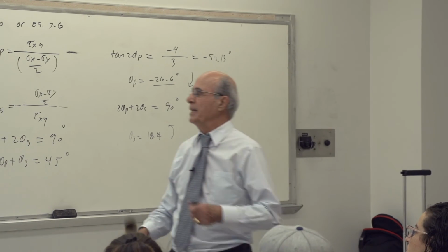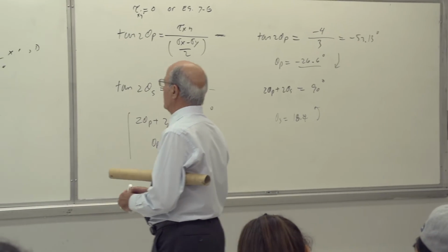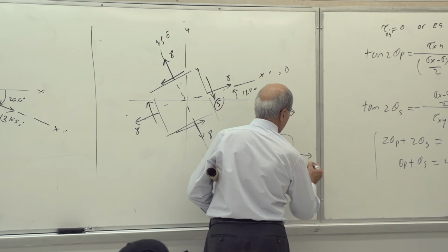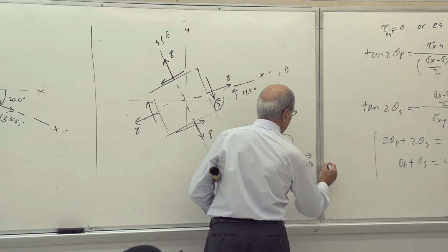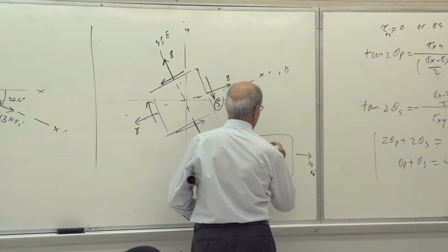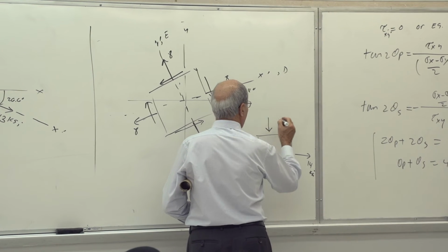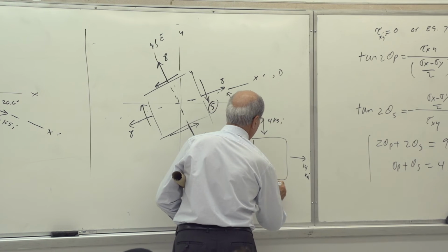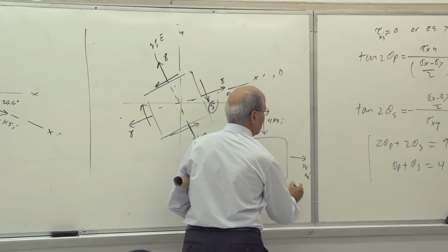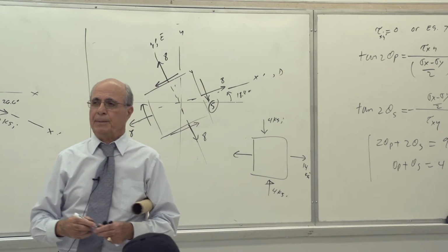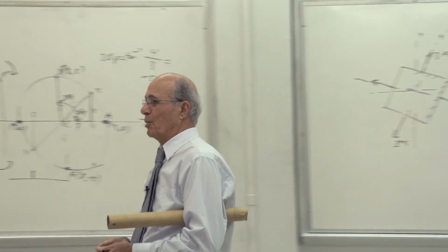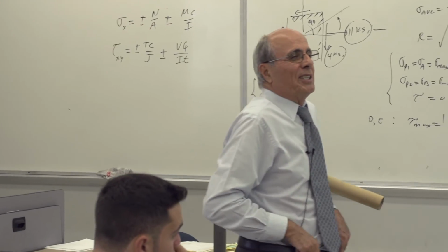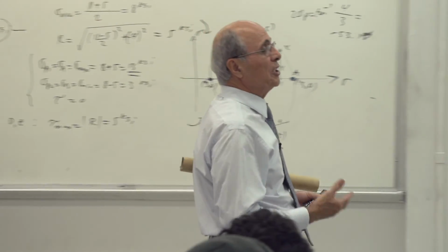This always happens. Now, I asked this question in the other class. If I give you a stress like that, and I put, let's say here, 14 KSI, and I put here 4 KSI compression. What are the principal stresses here? You don't answer. You probably know that question. What are the principal stresses here? I just want to see whether you see all of this or not.